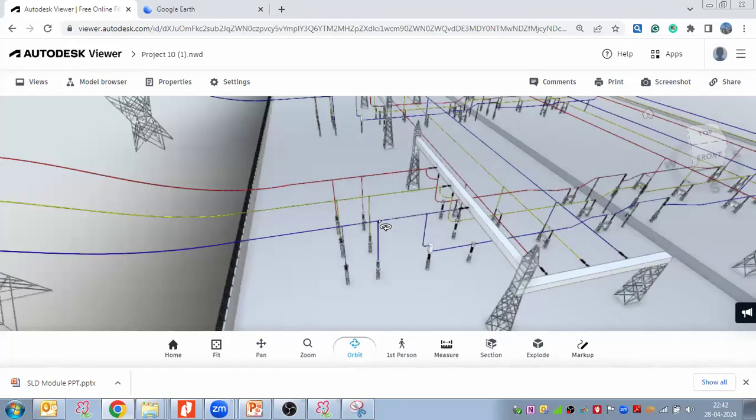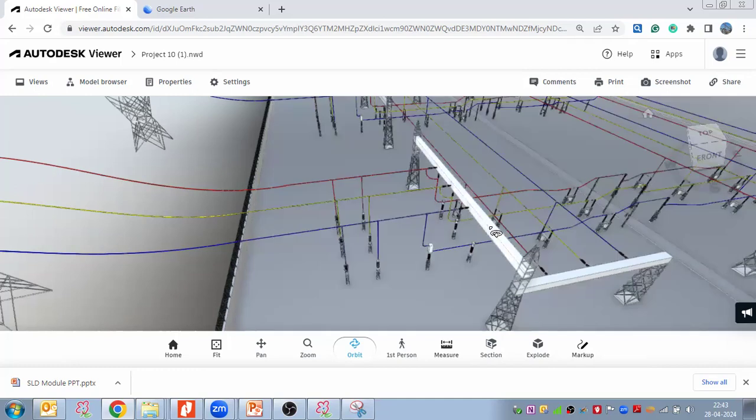No, sir. My doubt is, for example, here our line is coming as an incoming line. In the drawing which you are showing, that is an incoming line. So we have the starting equipment as a surge arrestor, after that CVT and the further equipment. But my case is different. This is the gantry structure. On the right hand side is our main switchyard, and from the gantry structure the line is going outside instead of coming inside. The line is going outside.